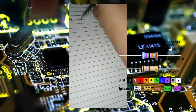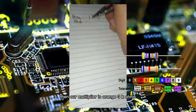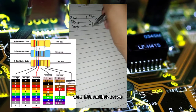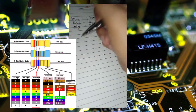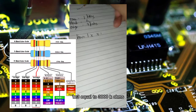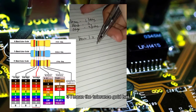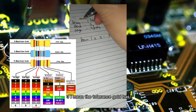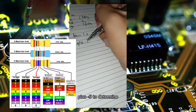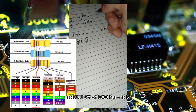Brown is 1. Black is 0. Then our multiplier is orange, 3, or kilo ohms. So 10 times 1,000 is equal to 10,000 ohms. Then the tolerance, gold, has plus and minus 5 percent, to determine the maximum and minimum value of this resistance.